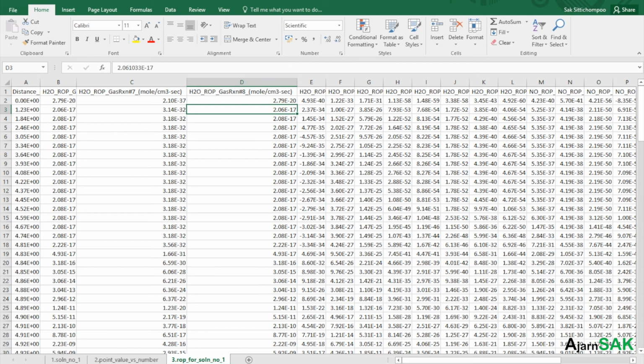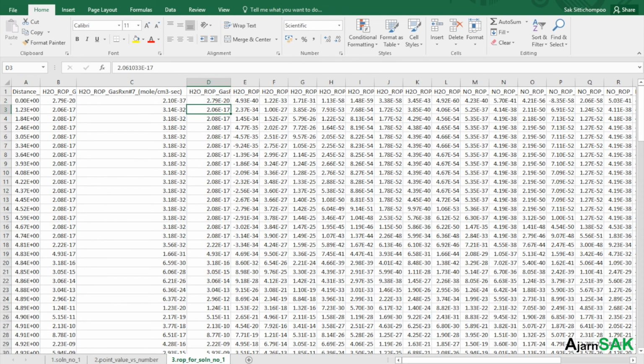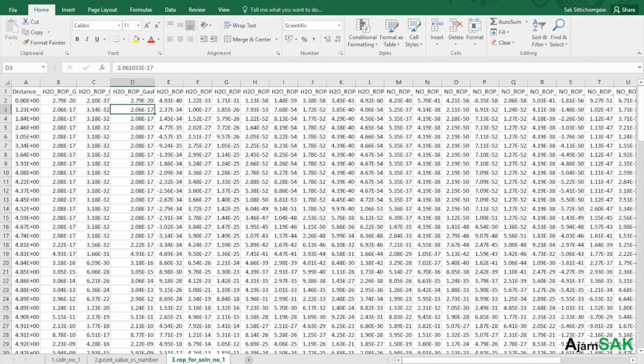You can do anything with this. So, for example, what I did was I was always looking into the NOx. Where NOx comes from, which reaction is most responsible for production of NOx, you can see from here. So I have to look for the highest number. Or what you can do here is sum all these numbers through your domain from 0 to 10.